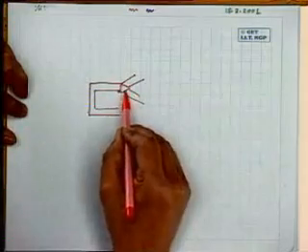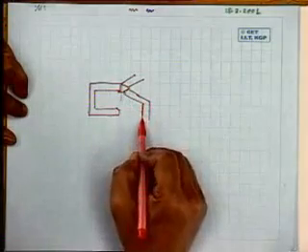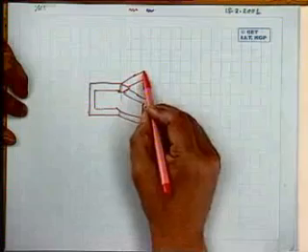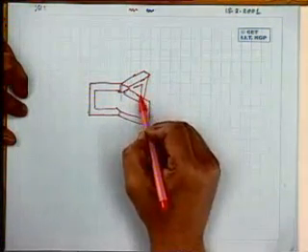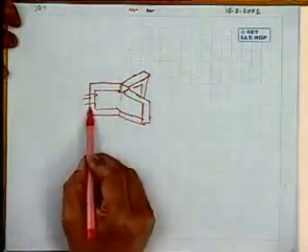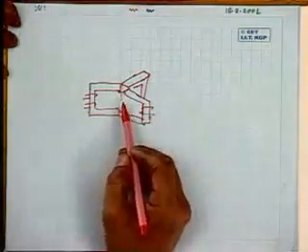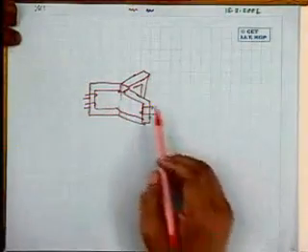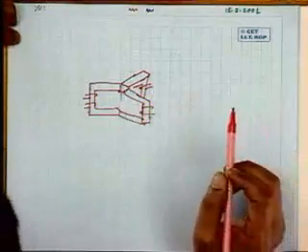In the central portion there will be no iron, like this. I think it gives you the idea. So here the coils are wound. Here the coils are wound. So this iron you can straight away remove, because it will never carry any flux under any condition, load or unload.